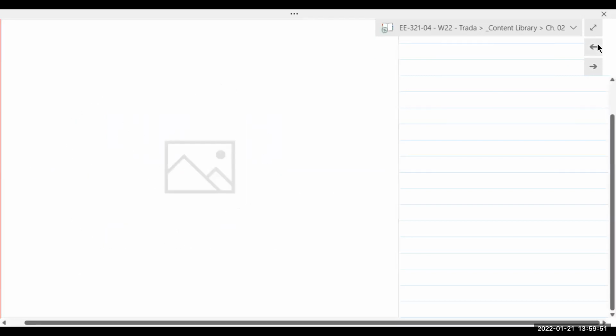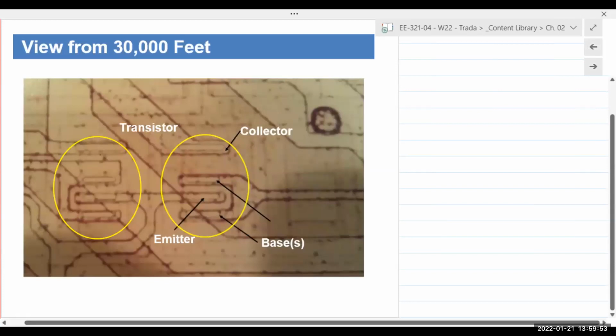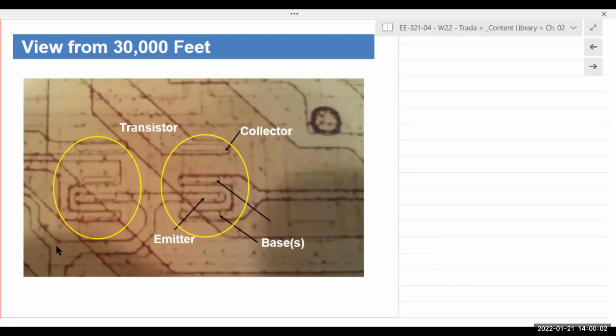So the image that we viewed earlier, which is right here, you see this is a complete transistor on the left and the right. But you had the collector, which is the entire work surface, if you will. Your entire work surface is the collector. You insert the base, and then you insert the emitter inside the base. And again, we actually have a clean room fabrication facility at Cal Poly, which not many undergraduate universities do. And there is a class that is offered every winter, in case anyone is interested.